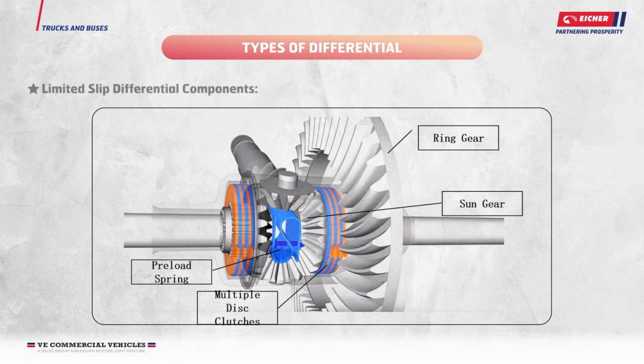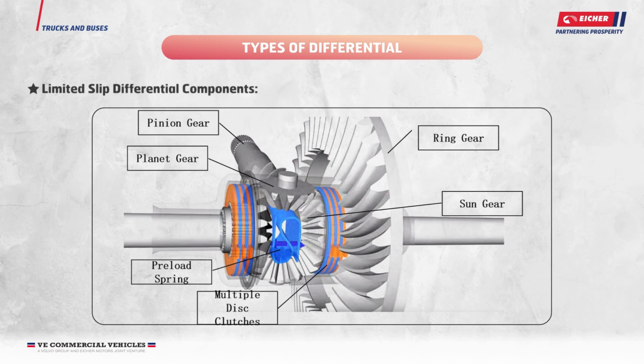Working of limited slip differential. The limited slip differential functions like a normal open differential during normal conditions and during turns, but if one wheel is on a higher traction surface, that is, the other wheel is slipping, the torque transmitted to it will be higher. So, the thrust force developed due to the bevel gear separation action also will be high at that side. Thus, the clutch pack at the high traction wheel side will be pressed firmly and the clutch pack will be locked.